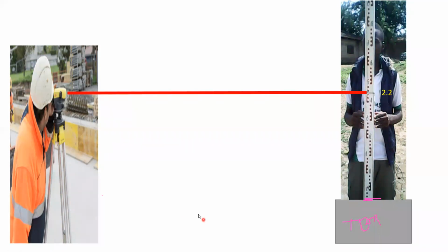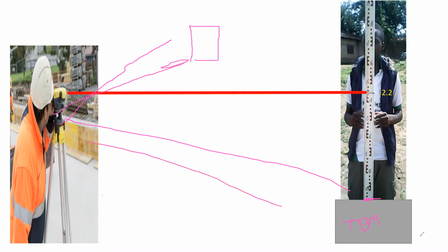Okay, you always have to make sure about the auto level that you're keeping. Let us say this is a footing where the level has to be given. From this footing, the auto level should be easily seen, and from the auto level, this temporary benchmark should be easily seen. That particular area we always need to consider, so that from here my footing is also visible, and the temporary benchmark is also visible. That is why I told you, in a big construction project we try to create 4 or 5 different temporary benchmarks, so that it will be easy for the surveyor to see both the footing marking, the footing level, and also the temporary benchmark level.